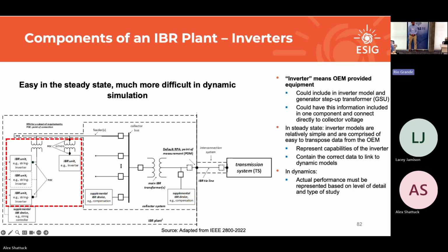Some of them have the step-up transformers there. Some of them don't. I'd say most of them have a GSU, an inverter step-up transformer. There are some manufacturers that just lump it all into one component that connects directly to 34.5. So it's not to say that if you don't see a GSU or an inverter step-up transformer it's automatically wrong, but that's a red flag to dig into. And as you do that a couple of times, you'll learn which manufacturers do that and which don't.